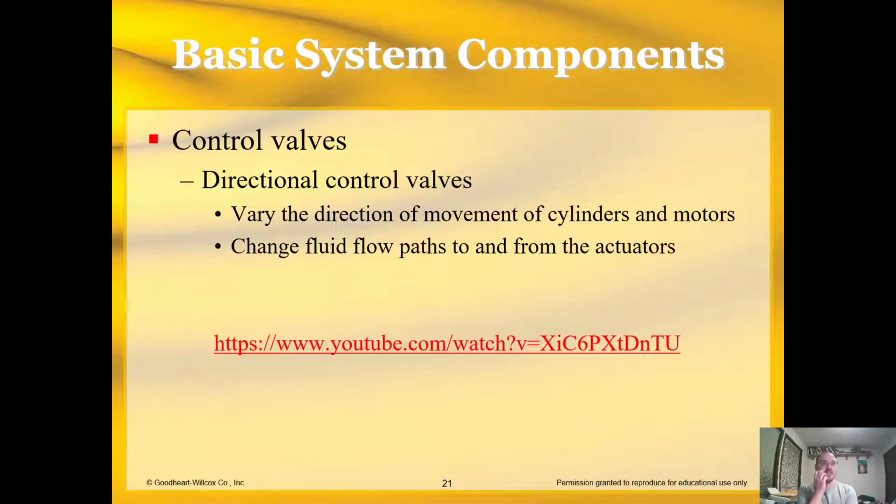Control valves. So directional control valves, this is the other group there. They vary the direction of movement from a cylinder or a motor. I mentioned that before. If we wanted to reverse the direction, we would reverse the directional control valve.